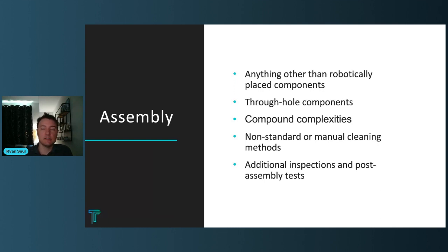And that's not even getting into the top side, bottom side issue, where, this is another common one, you see this with college projects particularly, you'll have physically large and heavy components on the same side as the most sensitive BGAs or QFNs that require careful thermal management, meaning that you're going to end up needing to reflow those parts upside down.